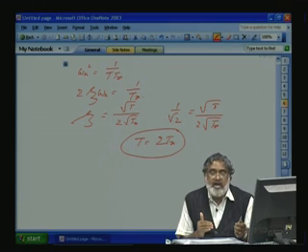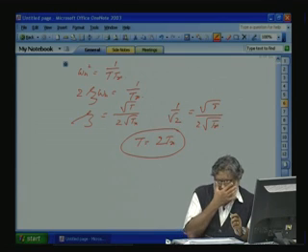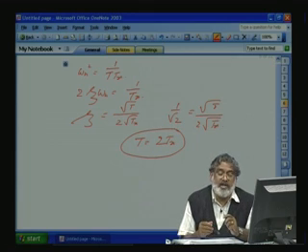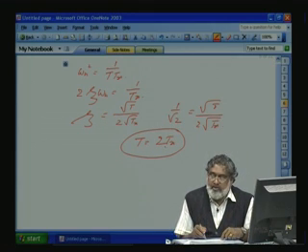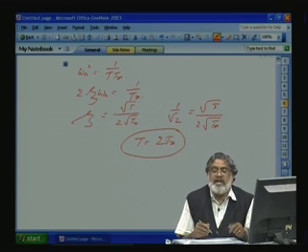So, current loop should act very fast. That means the frequency response of the current loop should be much higher than the outside voltage loop. So, let us put T equal to 2 Tr, put this into the current loop and then find out what is the controller required for the output voltage loop in the next class.